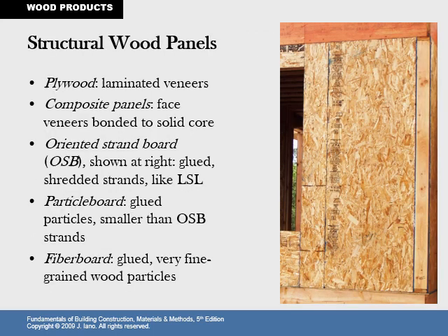Something that might deter termites and other bugs. Structural wood panels. Hurricane building has really gained a lot by strengthening using structural wood panels. It's plywood, laminated veneers, composite panels with face veneers bonded to a solid core. The oriented strand board, OSB, shown at the right, glued.